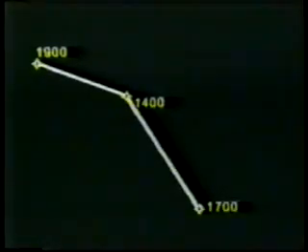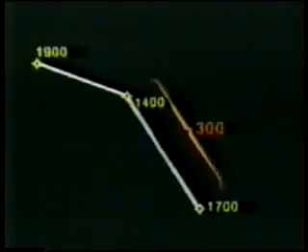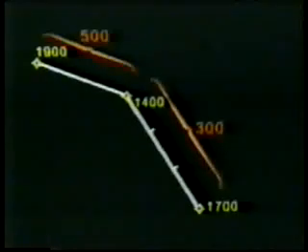These control points are joined by straight lines. The difference in elevation of the fault plane between well 2 and 3 is 300 feet, and since the contour interval is 100 feet, the line connecting them is divided into 3 equal parts. The difference between wells 1 and 2 is 500 feet, and 5 equal spaces are laid off along that line.